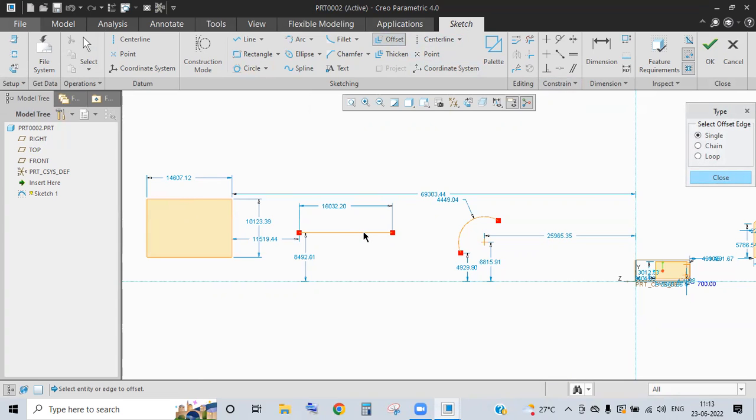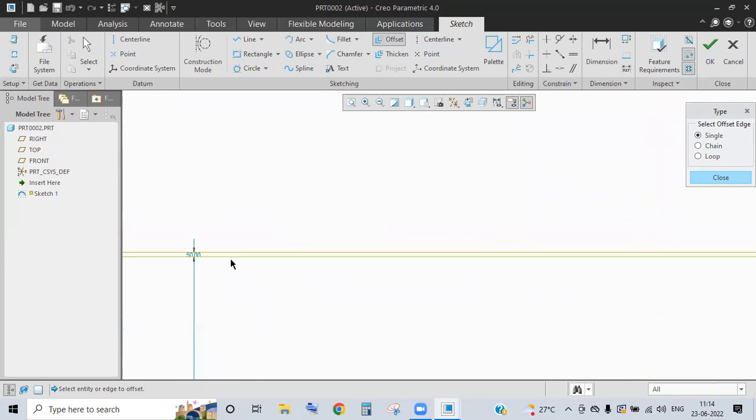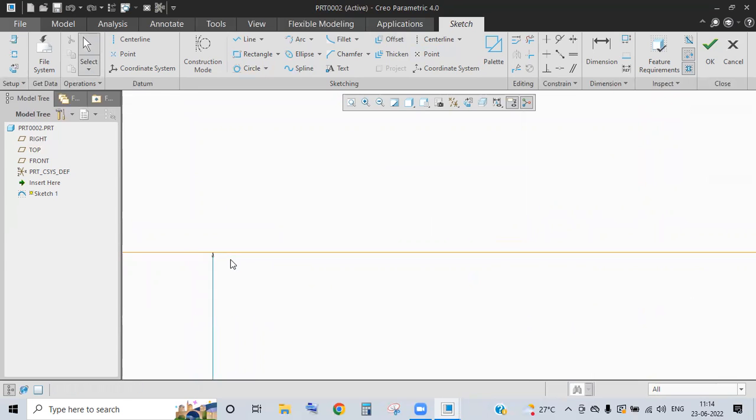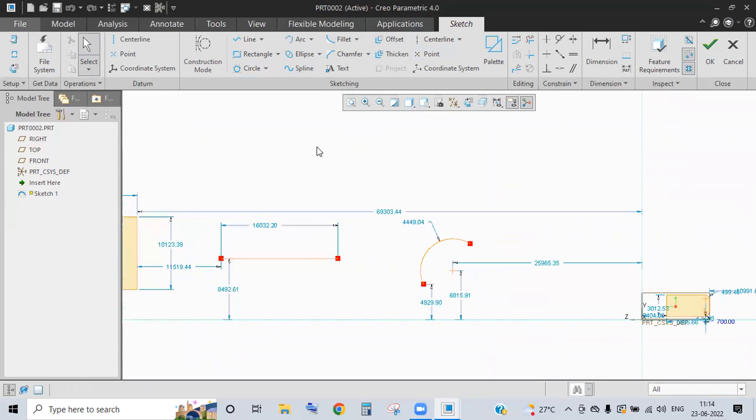Okay. Once I select it, select the single line. Now it is showing me some arrow, and it is saying enter offset direction of in the direction of arrow. Suppose I want the offset in that direction to be 50. Oh, actually these are in thousands, so 50 will not be visible. I need to give some thousand or something.